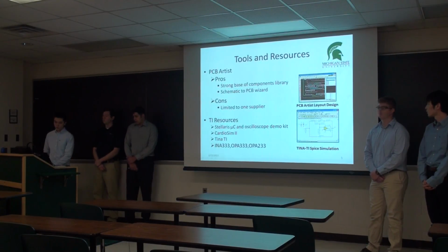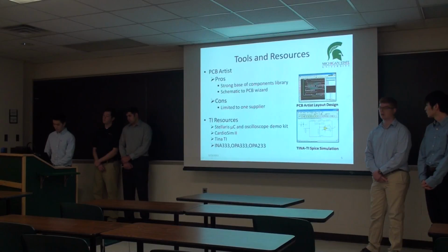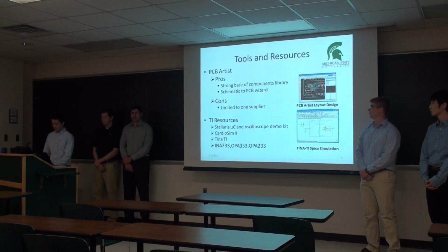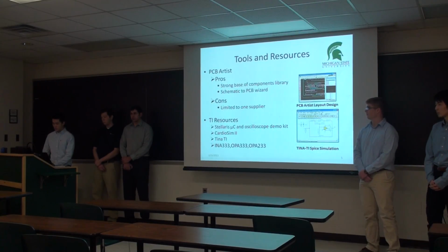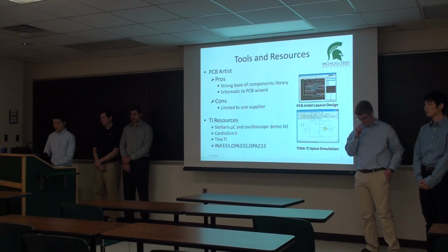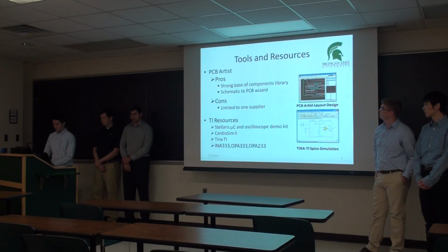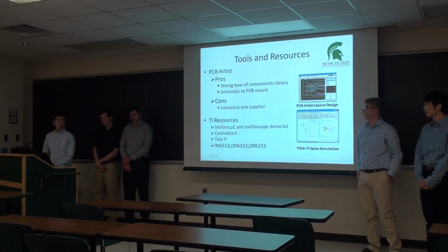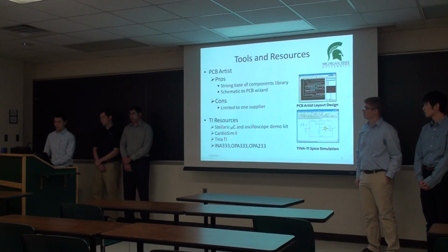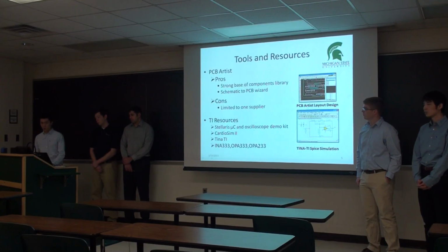And the tool that we use most is TINA-TI, which is a pretty excellent circuit simulation tool based on SPICE. Compared to other SPICE tools, TINA-TI features easy input of the circuit as a diagram, and it can provide all kinds of analysis that we need. We also get important circuit parts provided from TI, such as the INA333 that we use a lot in our front-end circuit.